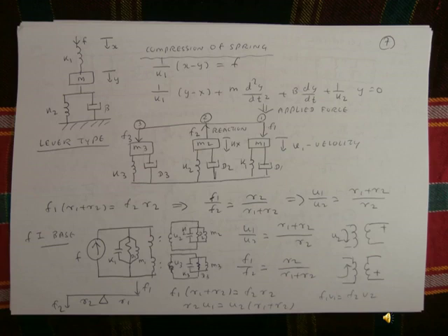So N1, K1, and D1 will be the primary side. And second, depending on this force, the lever transfers the force to the other 2 and 3 components. Those 2 and 3 components, the force is similar to the current flow in the transformer secondary winding. So the transformer secondary winding you can represent as U2, U3, and both the U2 and U3 are connected in parallel with the M2, D2, K2, as well as the M3, D3, and K3.